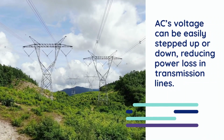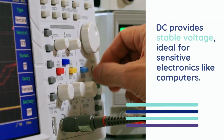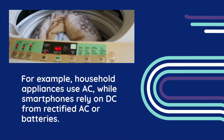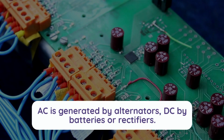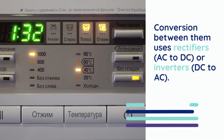AC's voltage can be easily stepped up or down, reducing power loss in transmission lines. DC provides stable voltage, ideal for sensitive electronics like computers. For example, household appliances use AC, while smartphones rely on DC from rectified AC or batteries. AC is generated by alternators, DC by batteries or rectifiers. Conversion between them uses rectifiers, AC to DC, or inverters, DC to AC.